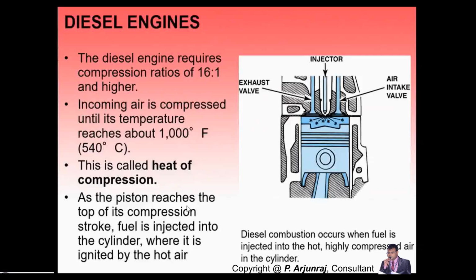So we have seen this even in the valve timing diagram. In the valve timing diagram, the fuel valve opens, and when the fuel valve opens, you get the injection. That will happen either 15 degrees or 20 degrees, with respect to the speed and different configurations of the engine. It can even be a 2-stroke or 4-stroke.